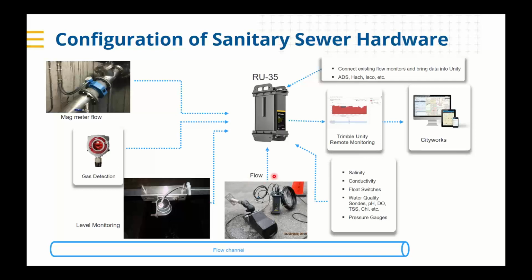We can conduct flow monitoring. What you see down there in that photograph is our Raven-Eye non-contact flow meter. That all ties into our RU-35, and you can conduct multiple studies with that for either I&I, capacity studies, pretty much anything that's needed to be tracking your collection system flows.